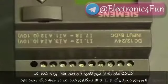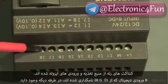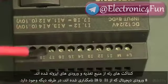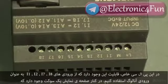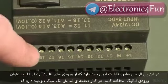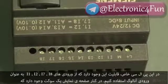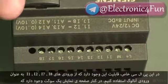On the other side, we have 8 digital inputs marked from I1 to I8. In case of this particular Logo, there is also a possibility of using I1, I2, I7 and I8 as analog inputs.